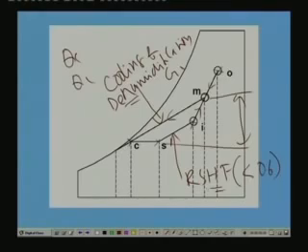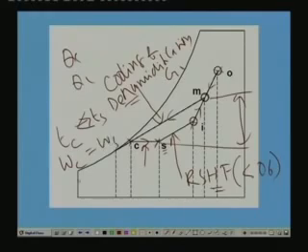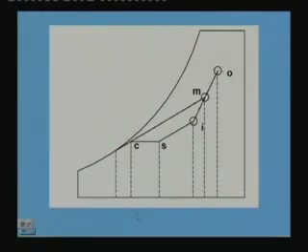For that purpose, at this point air flows through the reheat coil, and in the reheat coil it is sensibly heated. In the reheat coil the temperature increases from Tc to Ts, so that the point S lies on the room sensible heat factor line, so that it can take care of the latent and sensible heat loads. Since it is a sensible process, Tc will be lower than Ts, and Wc will be equal to Ws. So no change in the humidity ratio.